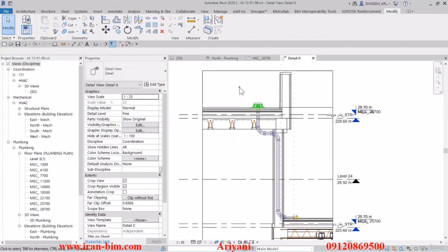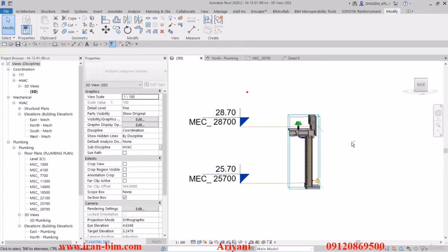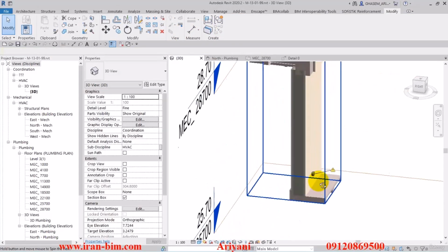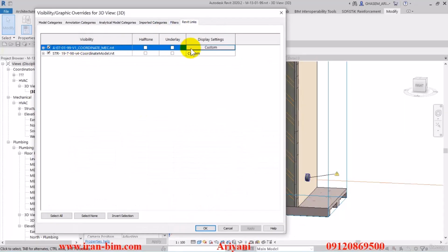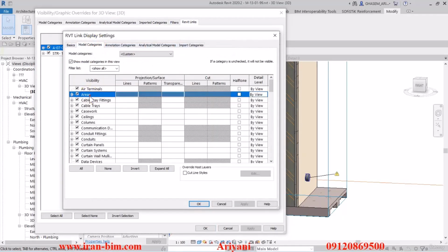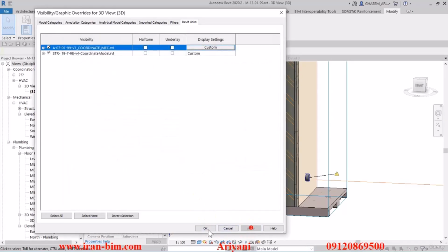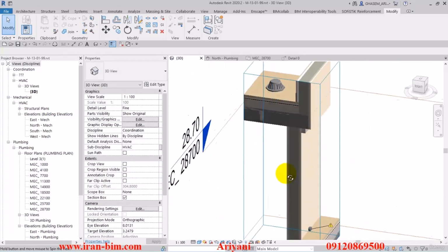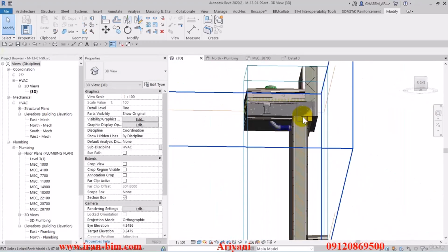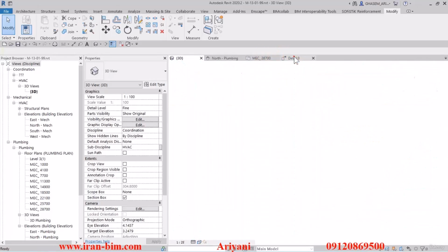So let's go over to the 3D view and select all of this area here, and we can see what exactly it looks like. Now this bit might look to be too high up, but it's because we hit the architectural floor. So we can go over to the visibility graphics menu, and then from the Revit links we'll put this on the model and activate the architectural floor. And there we go. Alright, so now let us proceed back to the cuts, and we can also see what it turns out like from this angle as well.